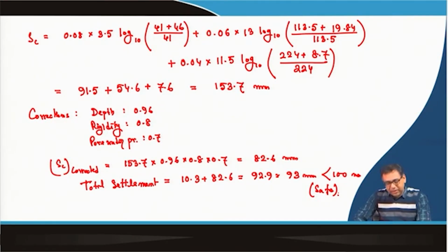Okay. But with that beam you can model different types of foundation, like the strip footing I have discussed. The strip footing you can model as a beam with infinite length, and you can model it as a beam with finite length. That means, you can model the beam under plane strain condition for strip footing, as a beam with infinite width, and you can model the beam with finite width also.